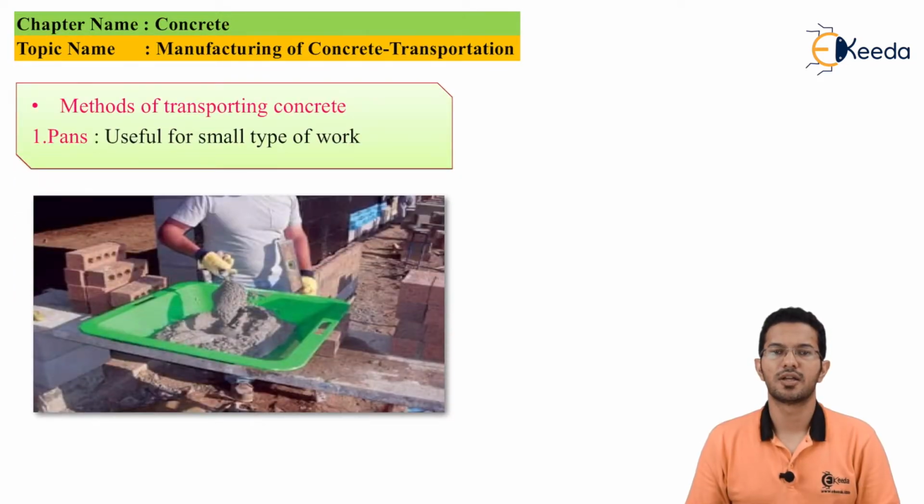The methods of transporting and placing concrete which are widely used are the pan method, discharged directly into forms through short chutes, by barrows, which are wheelbarrows and handcarts, power barrows or power buggies, dumpers and trucks which are agitating or non-agitating, monorail system, elevating towers and hoist, skip operated by cranes or overhead cableways, belt conveyors and boom conveyors which can be used in smaller locations, tremie pipes for underwater concrete. Any combination of the above can be used.